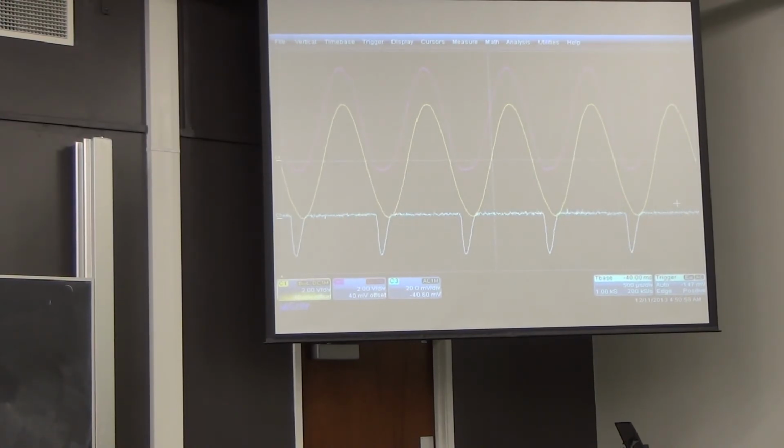What I've secretly done is I've got my diode and I've put a little resistor in there, and what I'm showing is the voltage across there. So as the diode conducts some current, we'll drop some voltage there, and that's why it's facing down, whereas in this case it's facing up, because I'm saying the current's flowing that way, we're expecting to read this voltage.